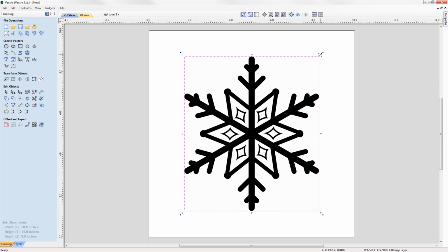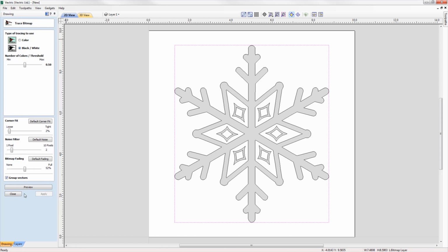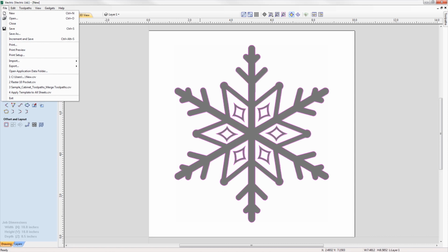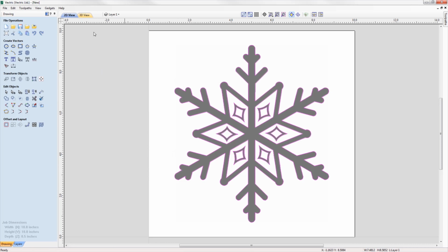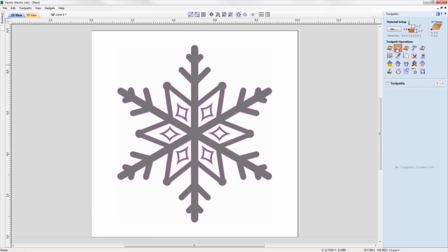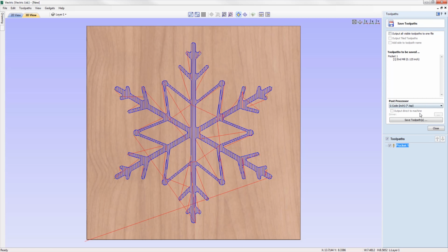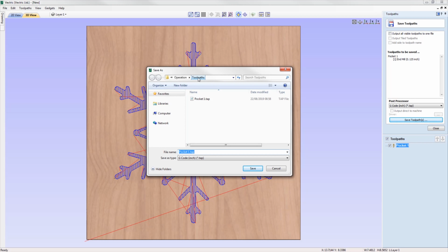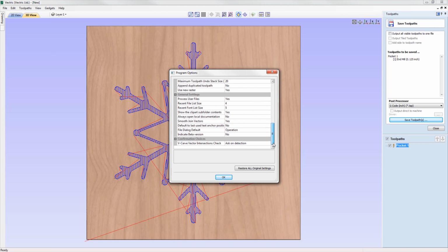I can then go ahead and create some vectors, and if I wanted, I could export those vectors out to the last location I saved or imported vectors from, which is from my vector folder. And then I can go ahead and create a toolpath from my vectors, and then look at saving out the toolpaths to my predefined toolpath saving location, giving me complete control over where I save things to for a more organised, efficient workflow. Alternatively, you could choose to always open the file dialogues in the folder of the current project.